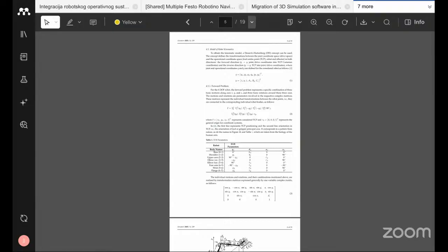Mathematical model. Think about the kinematics model and the dynamics model. The kinematic model is used to determine where the TCP will reach if the robot joint is shifting. Here we are not considering torque, mass, force, etc. Only the position and orientation are considered. That is called a kinematic model.